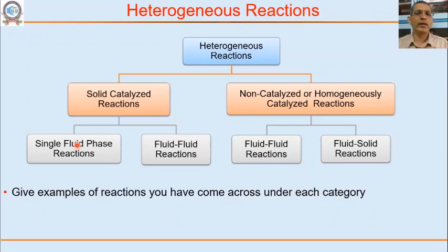So just to give you an example, gas solid, for example, you are doing FCC cracking. So fluidized catalytic cracking of heavy compounds like C20 plus or C18 C20 plus compounds in refineries. So they are vaporized and they are in the vapor space or vapor phase or gas phase, and the solid acts as a catalyst to crack these molecules into gasoline fraction, and therefore we could get higher yield of petrol and gasoline fractions. So these are called gas solid reactions.